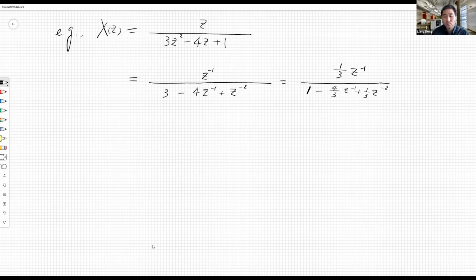Why do we do that? Usually this is indicated as H(z). So if it's H(z), you need to multiply this to the left of your equation, and this term corresponds to y[n], the current output. So I just want to make sure it's normalized. I pick up the current output y[n].